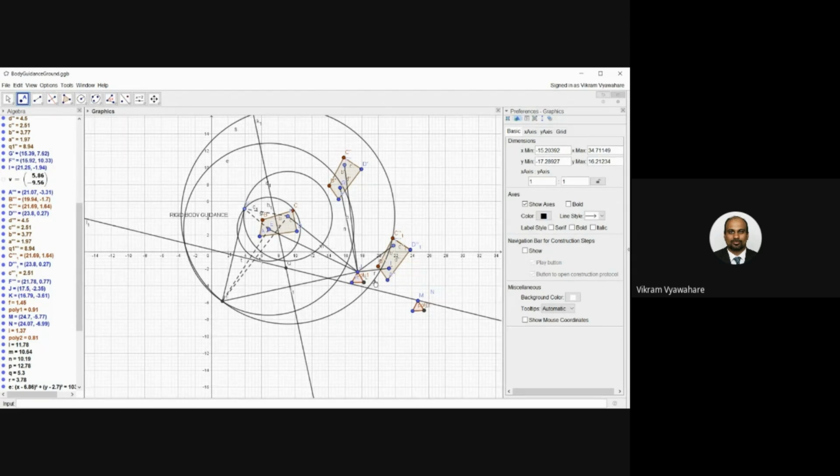So we will have from here to this point and to the next other center that will be determined, and to the next pivot. Like this, the mechanism will be there. So that mechanism will allow this motion. So you will say that this point is not on the first link also, right? So actually the link shape will have to be modified accordingly. You understand what I'm saying? This has to fall on the link. So you can maybe make a triangle like this. The other point also will come somewhere. So we'll have to make the link shape so that that point falls on the link. Okay.